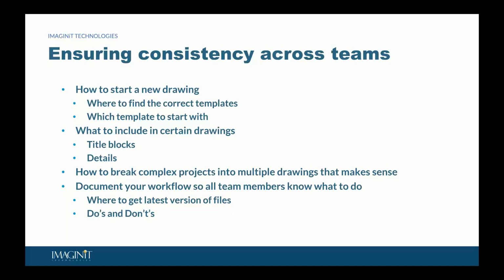So once you know that, now we start talking about documentation. You want to document your workflow so that all team members know what to do, where to get the latest version of files, and where we start talking about do's and don'ts. Things that we want to do. Do you ever want to work directly in a consultant's drawing that you're using as an XREF? The answer is no, you don't ever want to directly work in it, but you do want to clean that drawing to make sure that you don't introduce anything into your drawings when you XREF it in.